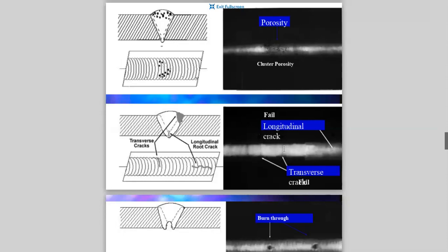But it's not necessarily a bad thing. As long as it's got good connection with the base metal and it's not spalling off or chunks of it aren't breaking off, then that's fine. This stuff is just so hard and brittle sometimes when we're putting that hard facing on, that if you don't cool it absolutely perfectly, it's just going to crack a little bit. It doesn't mean the weld has to be ground out and redone if you're doing hard facing. But yeah, it's not something we want to have in something like a 7018 weld. I've never seen that happen in a 7018 weld.